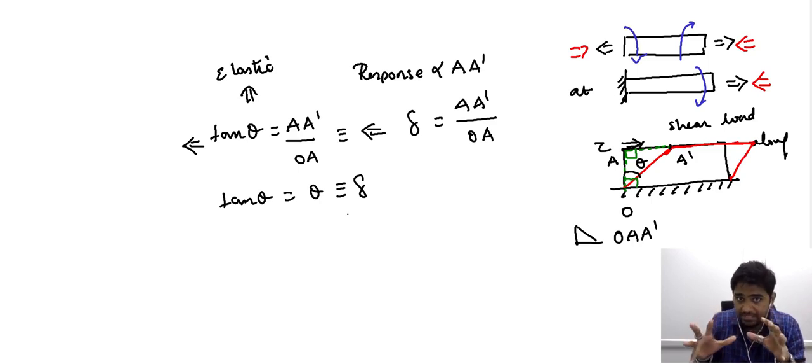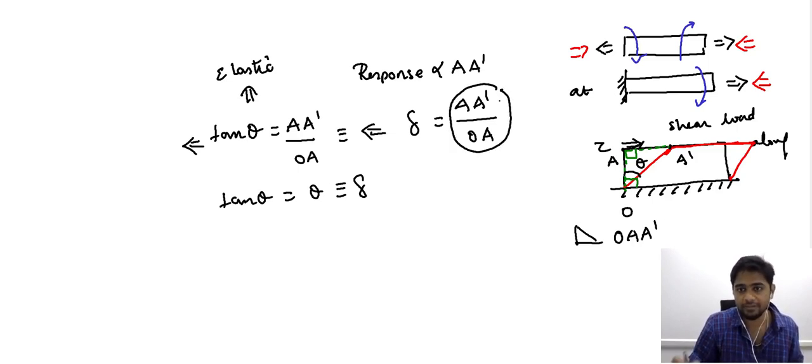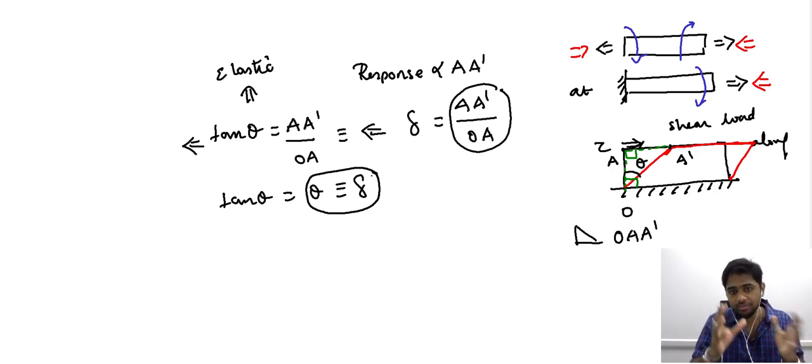So now what we have here is two descriptions, that is the ratio of shift in the corners with respect to one of the sides, the shifting sides of the sample, and the angle that is introduced because of the loss of the orthogonality. Both of these describe shear strain, which is nothing but the response offered by the material.